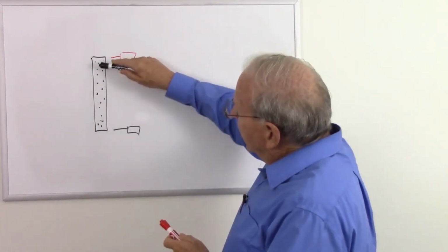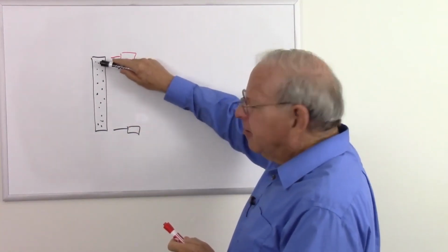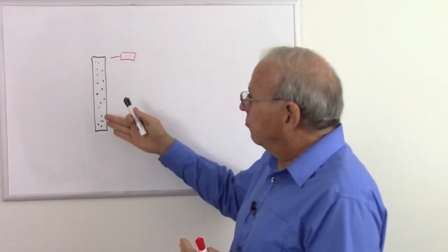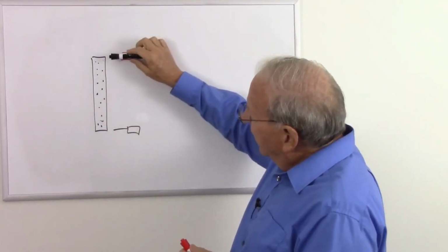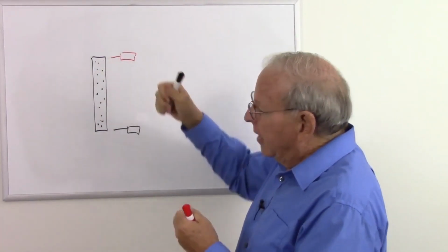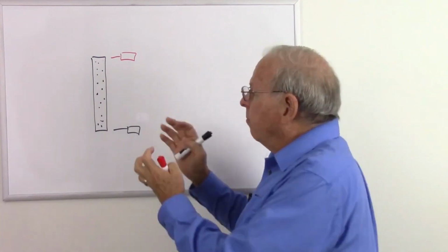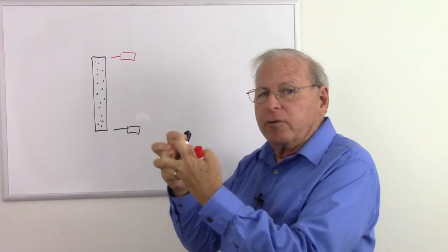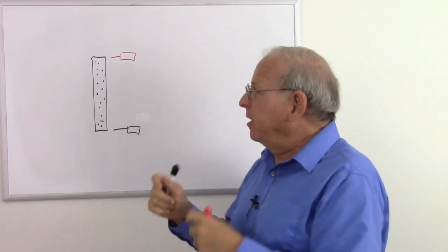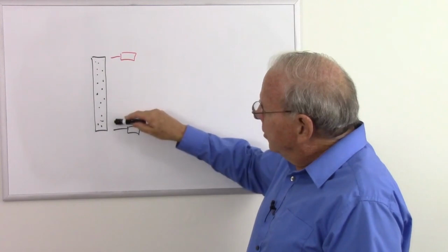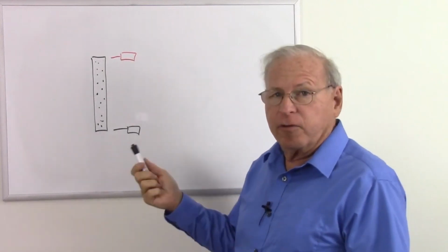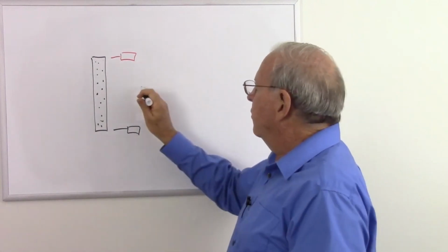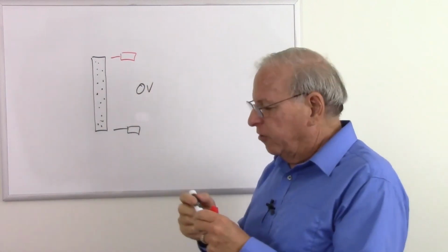So these electrons are pretty much like air molecules in a soda straw, which I often use as a demonstration of how a wire works. They're just floating around there freely and they're not bunched up anywhere. We aren't pushing them to one place and forcing them into a corner where they will want to push back, where we will build up any kind of pressure. So there really is no difference in pressure from one end to the other, or difference in voltage. Remember, voltage is electrical pressure. So I expect this voltmeter at this point to read 0 volts.